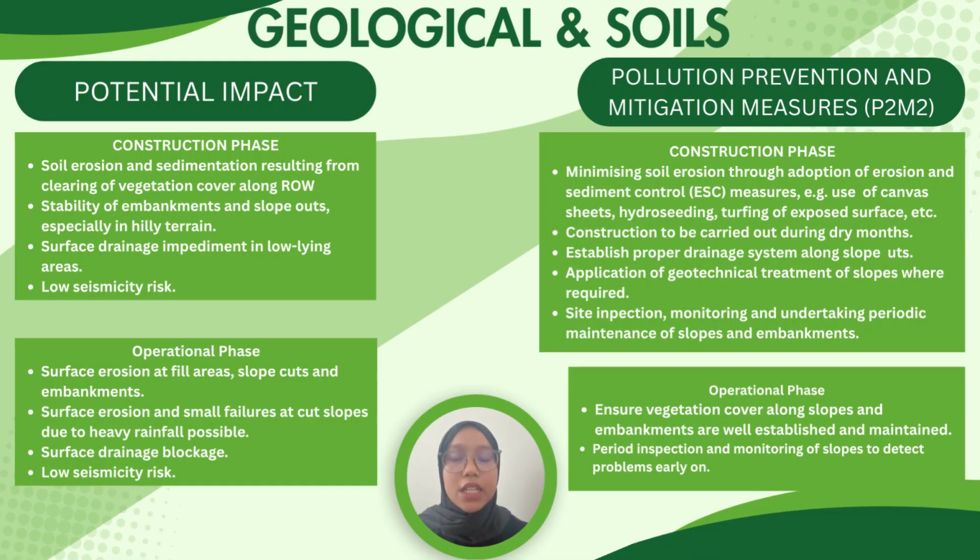Next, I will present the significant environmental impacts related to geology and soils, together with the proposed mitigation measures. During the construction phase, land clearing and earthwork may cause soil erosion and sedimentation, which can affect nearby drainage systems and waterways. Slope cutting and filling activities may also increase the risk of slope instability and localized waterlogging. Although the project area has a low seismicity risk, construction vibration may affect loose soil conditions.